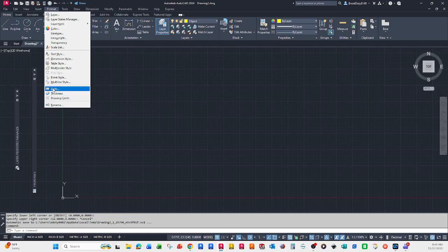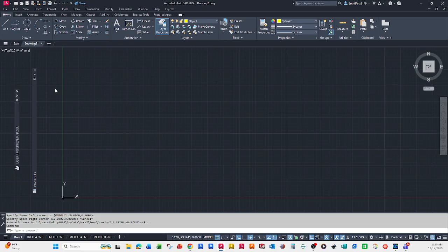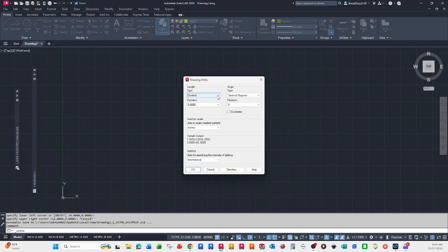Now, when we talk about units, when I say you need to look at the units of your drawing or your project to help determine the limits, well, I'm not talking about go set your units here. The only time that you're going to change this is if you're not doing mechanical drawings. If you're doing architectural drawings where you need to see feet and inches, or decimal feet, whichever, then you're going to use architectural for that.